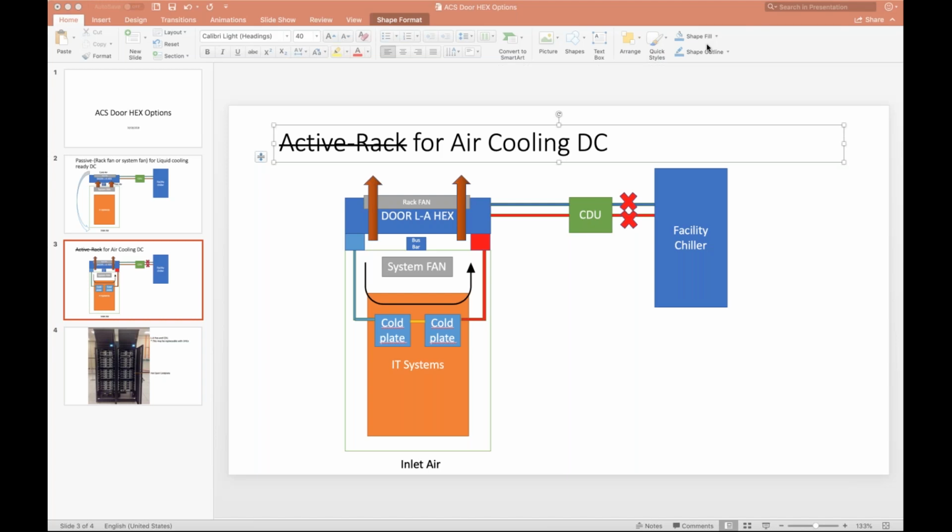It's also really important to pay attention to your water quality on the secondary loop in the white space, because really these systems are quite reliable unless you have corrosion within the secondary loop, which could cause potential for leaks over a longer period of time. But there's certainly multiple methods to reject the heat outside the data center beyond using dedicated cooling plant. For sure, agree.